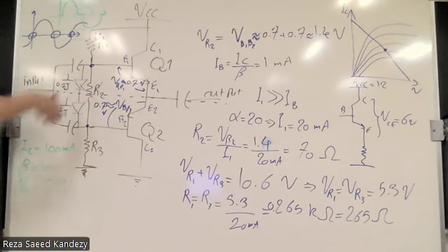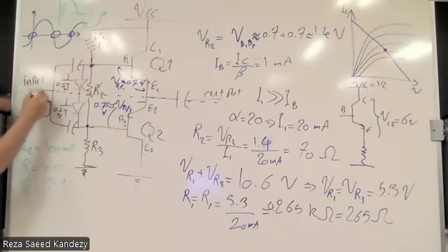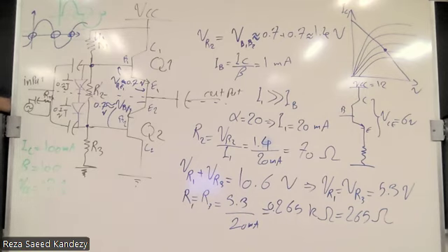For the AC one, it conducts. So you have an AC source, you have your capacitor, and you have your Thevenin resistor. Now, you have a 10 hertz signal or a 1 kilohertz signal. You can design the cutoff frequency, which is 1 over 2 pi RC, at a value that makes sure you do not attenuate your input.